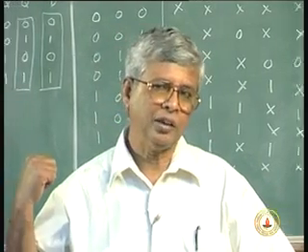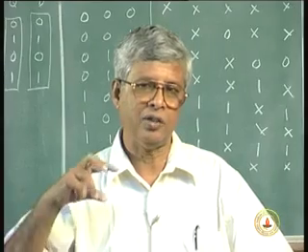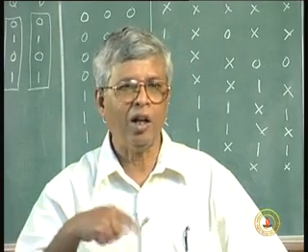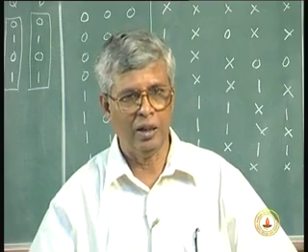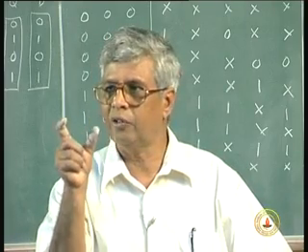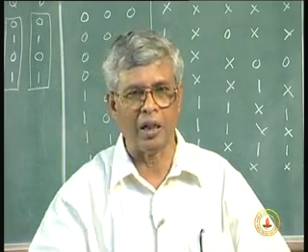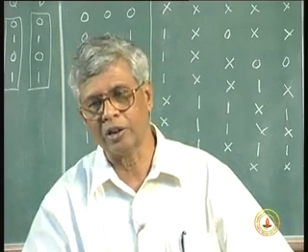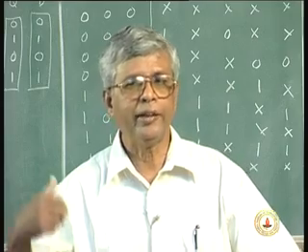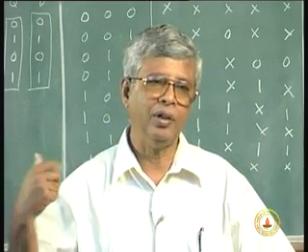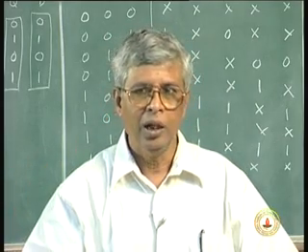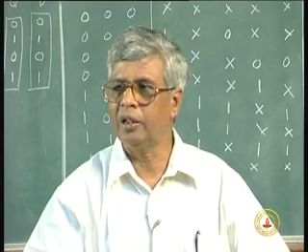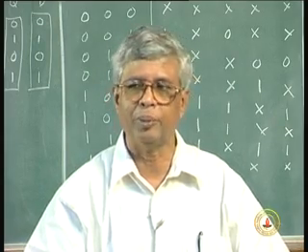The 2 circuits we discussed are very simple circuits. I have taken circuits which do not have an external input. That means every clock cycle the circuit has to change its state. Each state the circuit will remain in only for the duration of one clock period, and then it will go to the next state, and then to the next state. Of course, I can complicate this by giving external inputs, then the steering logic will also take into account the external inputs in addition to the present states.